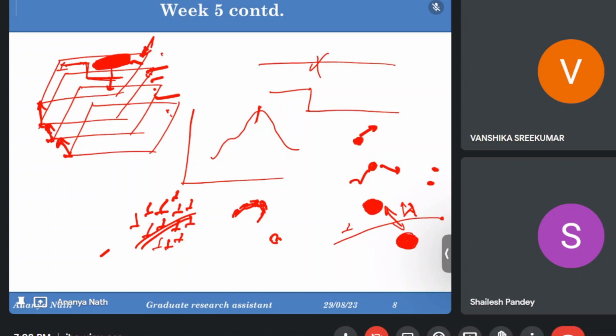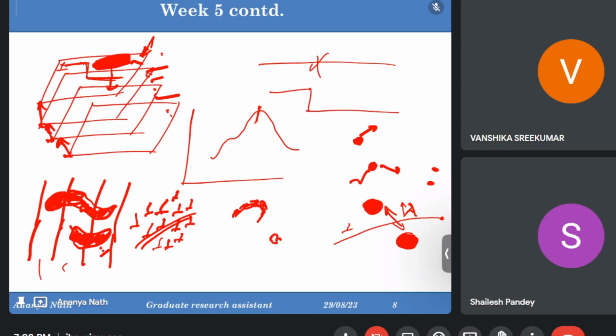So what happens is, if there are some planes, this dislocation was previously here, but now it will try to move forward. After some time, this dislocation will come to this plane, and now it's in this plane only, not in this plane. This is plane 1, 2, 3. Previously it was only at plane 1. Now it has crossed over and come down to plane number 3, and this is how it moves. And this phenomenon is called cross slip.